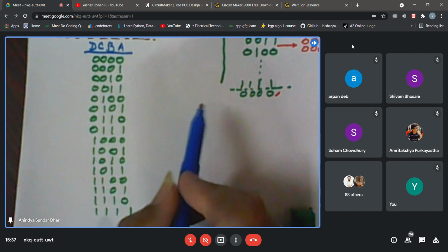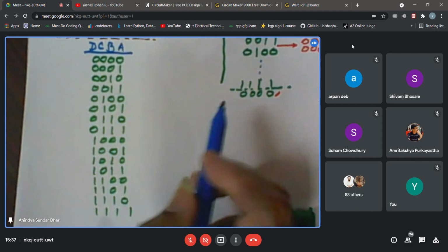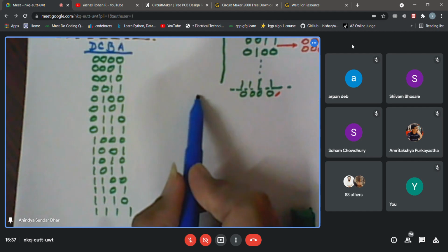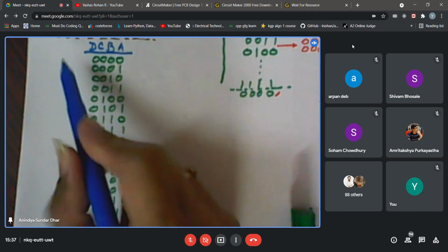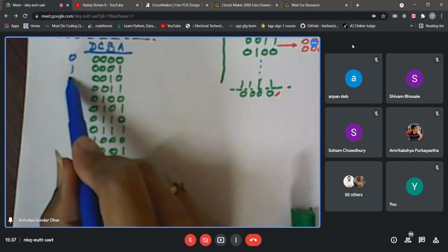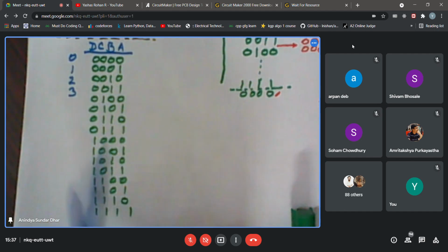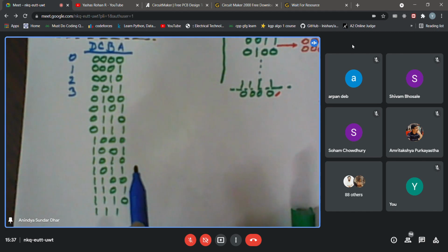What will be the output I will be requiring from a mod 4 counter? Equivalent states of 0, 1, 2, 3. Right? After 3, once again I require 0. So is there any other solution than what you have suggested? You suggested C to connect. C, where should I connect? To both the resets. Okay, both the resets, so it will work certainly.